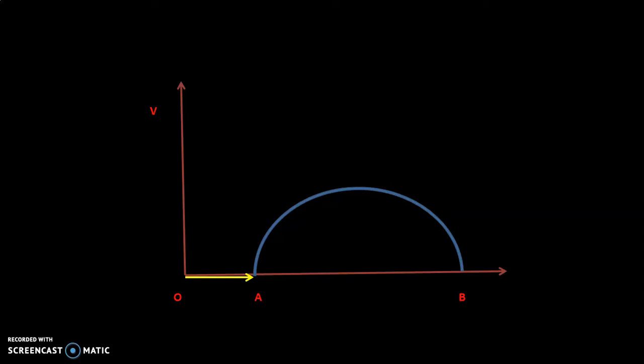As we discussed earlier, our dispersion coefficient is the ratio of magnetizing current to ideal short circuit current. From the graphical view, we can see that OA is our magnetizing current and OB is our ideal short circuit current, so the ratio of OA to OB is the dispersion coefficient.